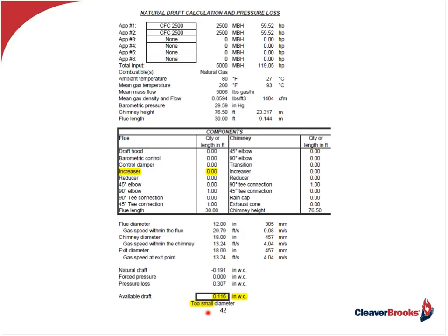This confirms Steve's earlier discussions about not considering the increase in mass flow when adding a second boiler to the exhaust system, resulting in back pressure increases and poor burner operation, including pilot failures for the downstream boiler. The condensing style boilers are more susceptible to these pressure fluctuations.